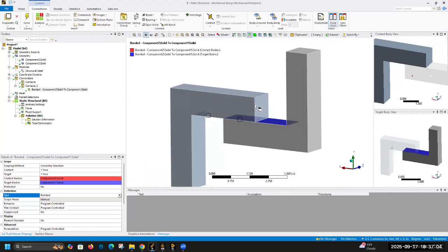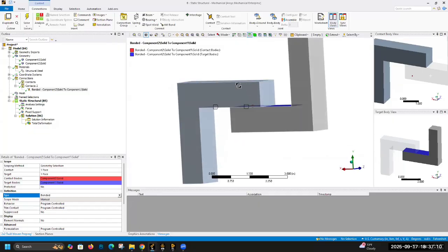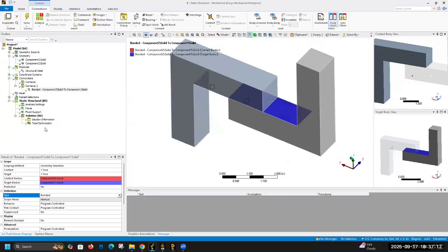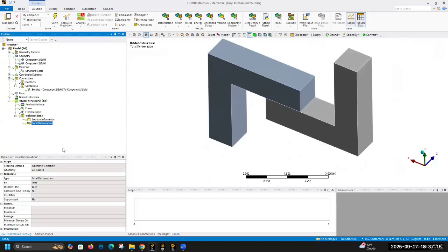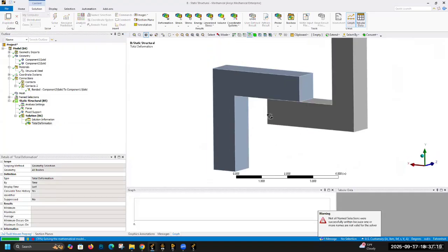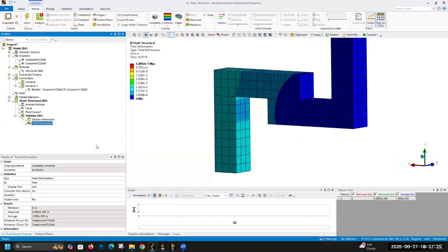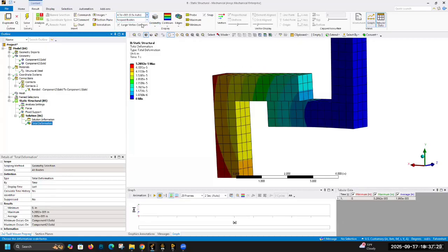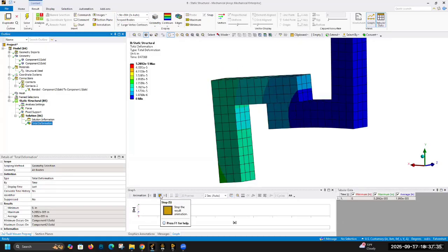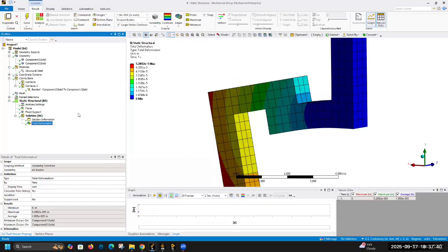I've seen this happen before, where someone will import a geometry from CAD and they'll say, okay, great, and then they'll apply a force and get stress results. But you might be getting stress results because your contacts aren't realistic compared to the real world, and I think that's pretty dangerous. You want to know what you're putting into your model before you run it. But yeah, this would be the default where it's bonded, so it's effectively acting as if it's on top. Gotcha. All right, thank you.